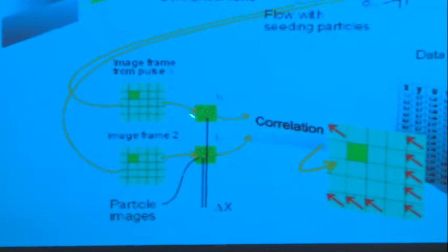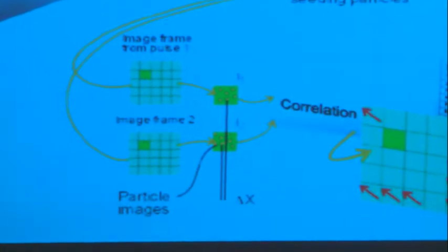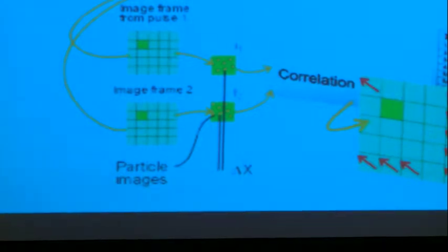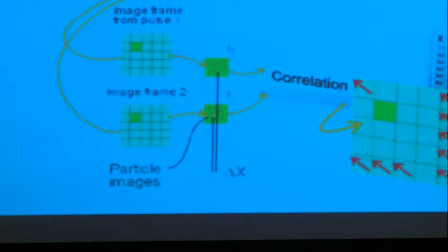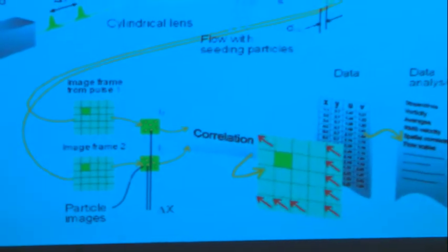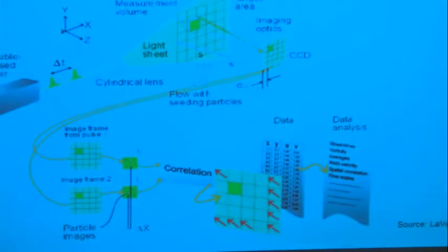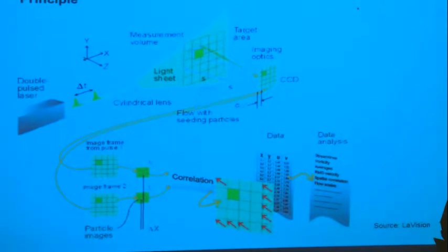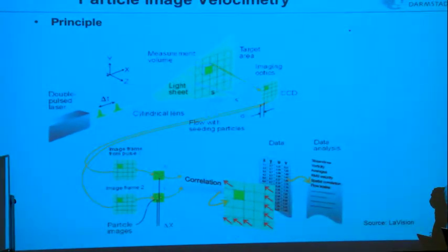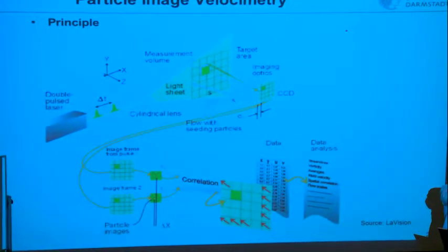In the magnified view is a sketch where you now see as these dots the instantaneous locations of the particles. So the idea of PIV is that you just look for the most probable shift of this particle pattern between these 2 exposures. Let's say you had 3 particles in the first image, and then you're looking in the second image, where have they moved to?